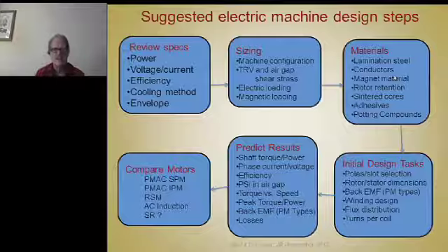You can also replace laminated cores with sintered cores. There's a lot of new materials available for magnetic materials made out of sintered parts. It allows you to achieve quite complex shapes of magnetic cores that would be difficult to achieve through a stamped, punched, laminated structure. Then, of course, significant progress has been made in recent years on potting compounds and encapsulating materials. And we're going to talk about that at great length as well.